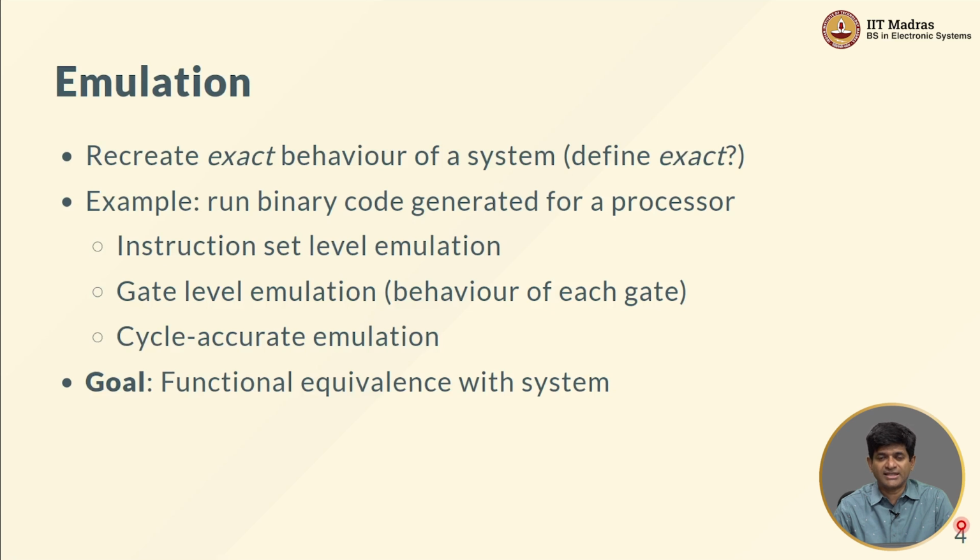The only real difference is that every time that I evaluate a gate, for example, there is some function being evaluated behind the scenes, right? But it does not necessarily correspond to the transistors and other various aspects that are there inside the gate. Now, emulation also works at a certain level of abstraction. I do not plan to emulate the behavior of logic gates by going all the way down to transistor circuits. However, what I would like to do is to emulate the behavior of larger systems, right?